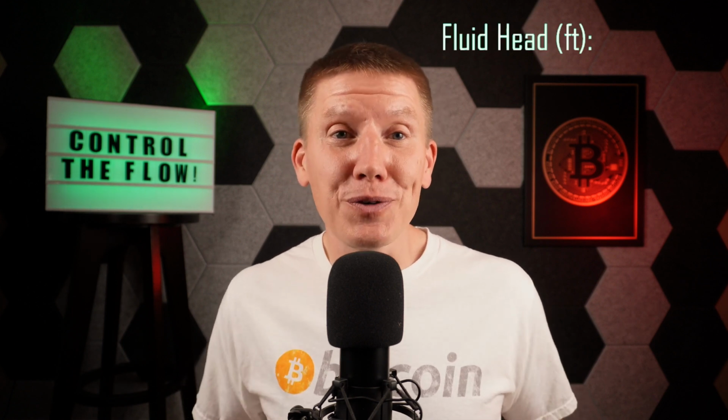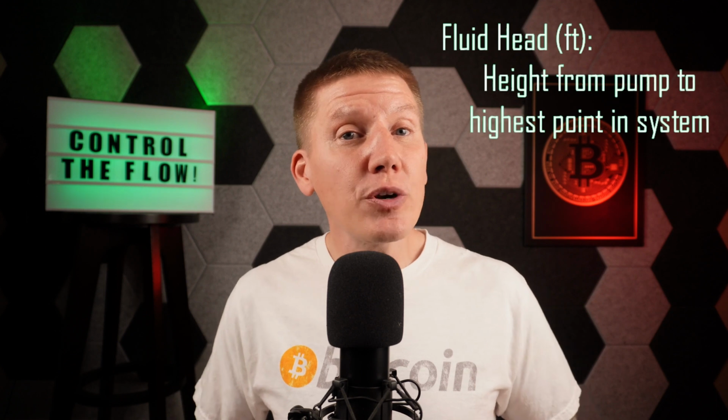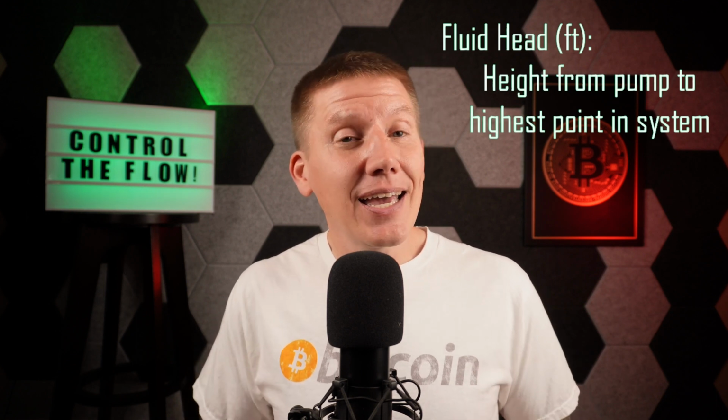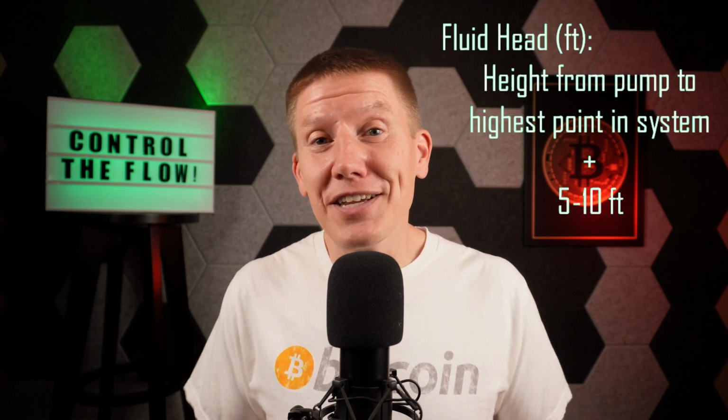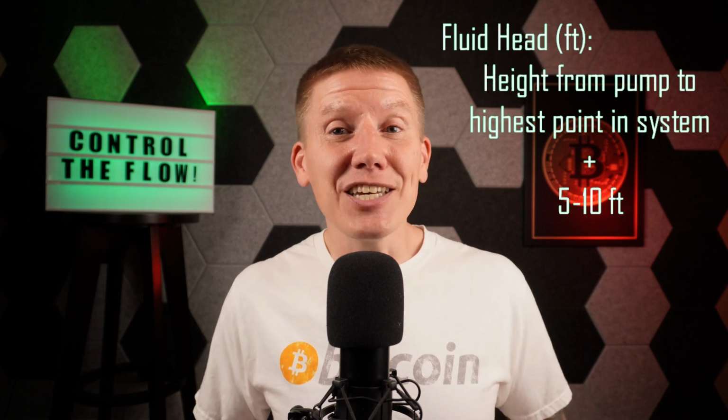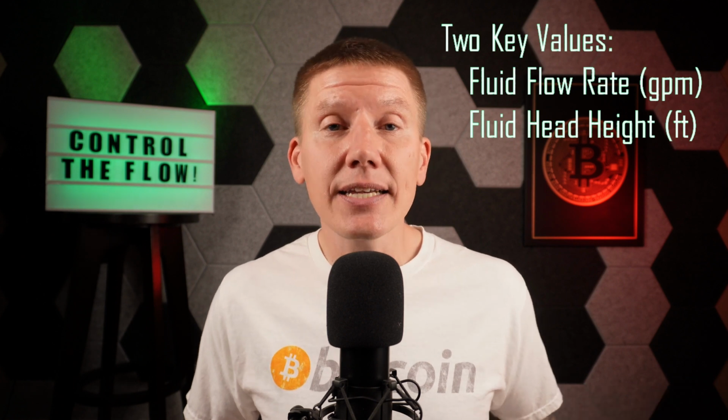So the way you want to do this is start with the height difference between your pump and the highest part of the system, and then maybe add 5 to 10 feet to that number. Guessing high is probably a good idea because you can always throttle back your pump with a valve attached to the output. So with those two numbers in hand, the flow rate and the estimated head height, now things get